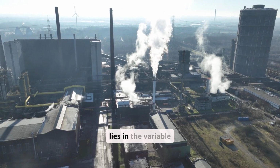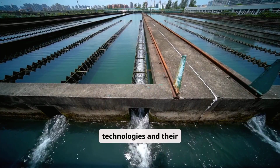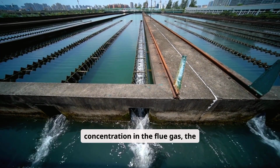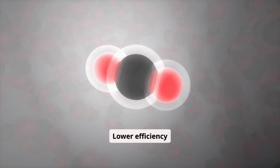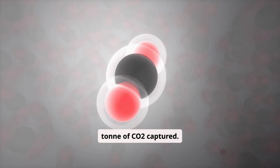Another challenge lies in the variable efficiency of different CCU technologies and their applications. Capture efficiency can vary significantly depending on the CO2 concentration in the flue gas, the specific capture solvent or sorbent used, and the operating conditions. Lower efficiency translates to higher energy penalties and increased costs per ton of CO2 captured.